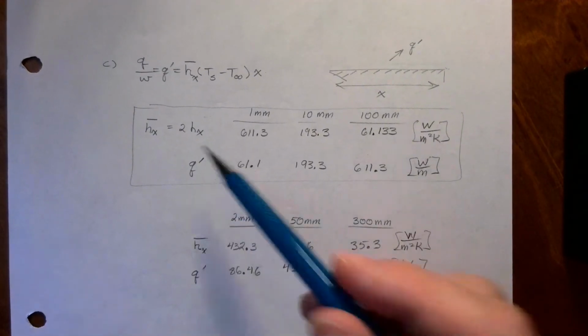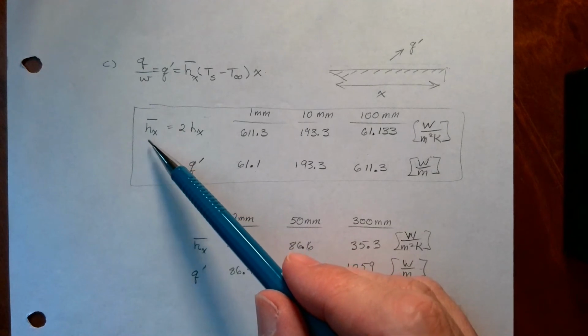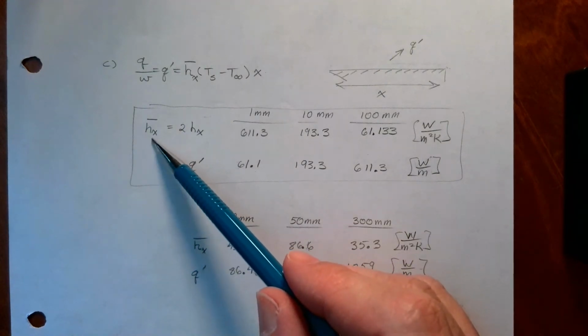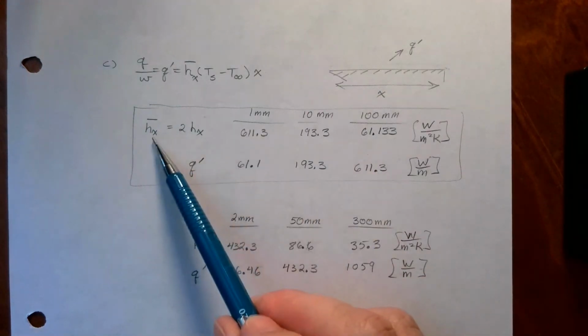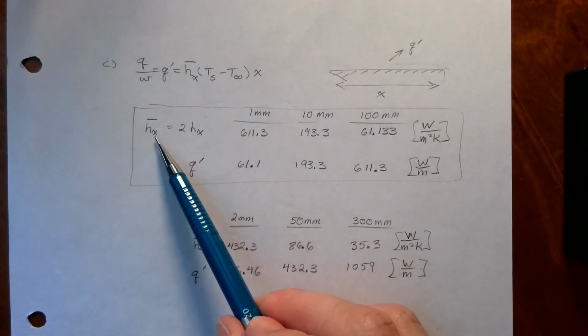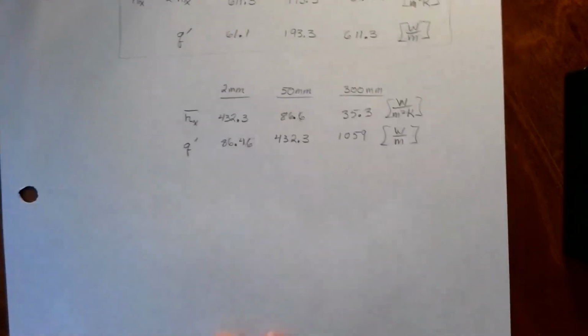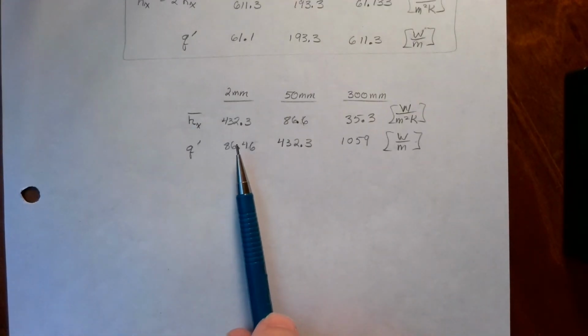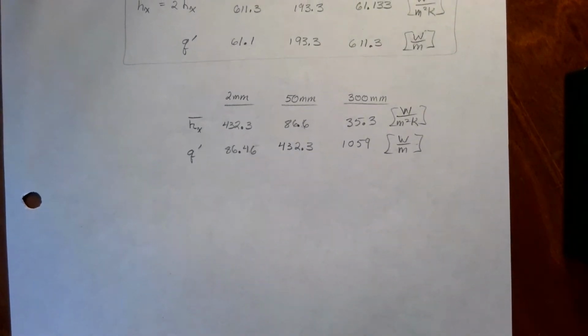And what I would recommend is that you go get the average Nusselt number correlation, and from that calculate this H bar. You will get exactly the same answer, but it's good to have the experience of interacting with the correlations. And then down below, I'm not sure why, I've actually calculated the answer at different locations as well.